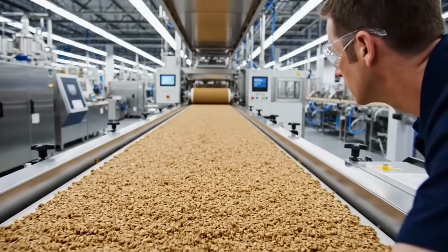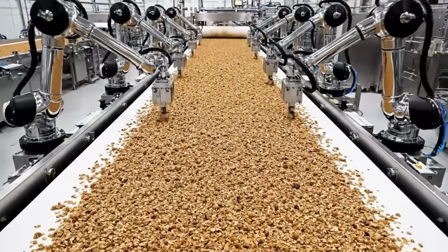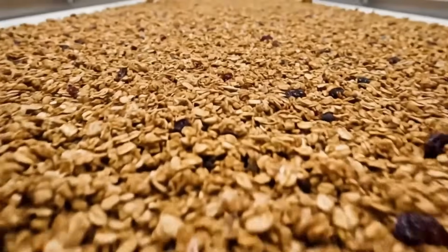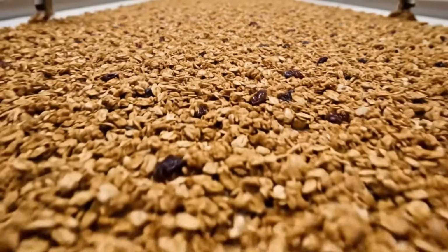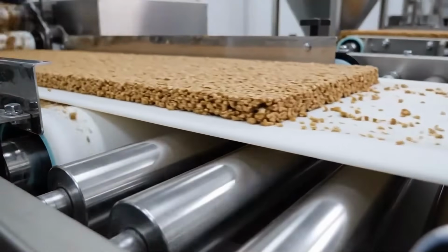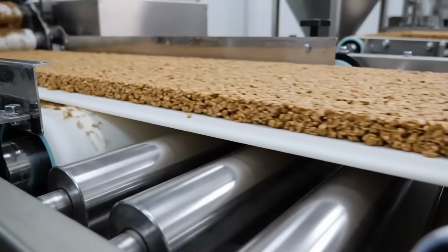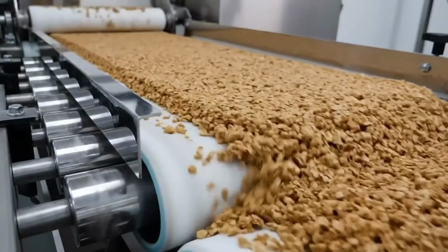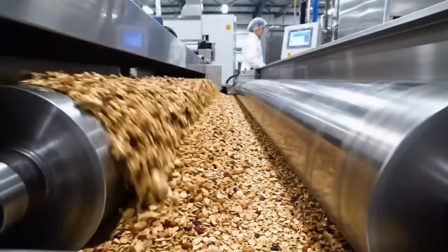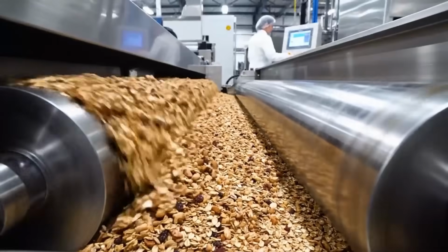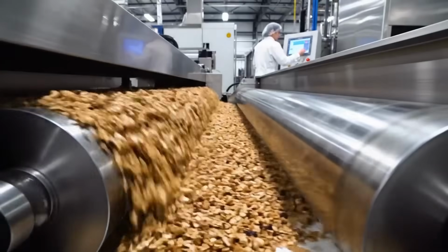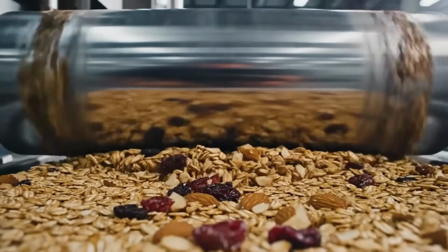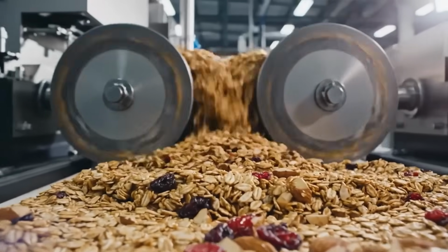Setting the slab depends on product style. For baked oat bars, the slab enters a tunnel oven. Baking drives off moisture and sets structure by solidifying sugars and fats. Oven zones are tuned to avoid overbrowning while reaching a target moisture endpoint. Airflow and temperature control surface drying and internal set. The slab must be firm enough to cut cleanly, but not so dry that it becomes brittle.